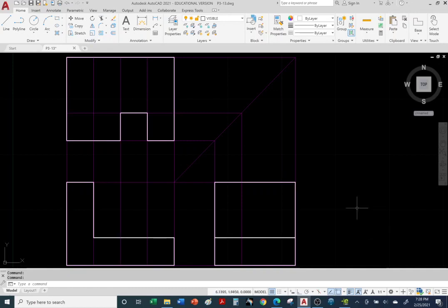Those of you that want to turn on or turn off your dynamic input: anytime you use a command, for example, we're ready to use the line command, click on line command. You can type in coordinates if you have dynamic input, so that we can do things on the fly by simply typing in your X and Y coordinates, or you can even type in a length and an angle. I'm going to turn off my dynamic input. You can leave it on if you're comfortable with it.